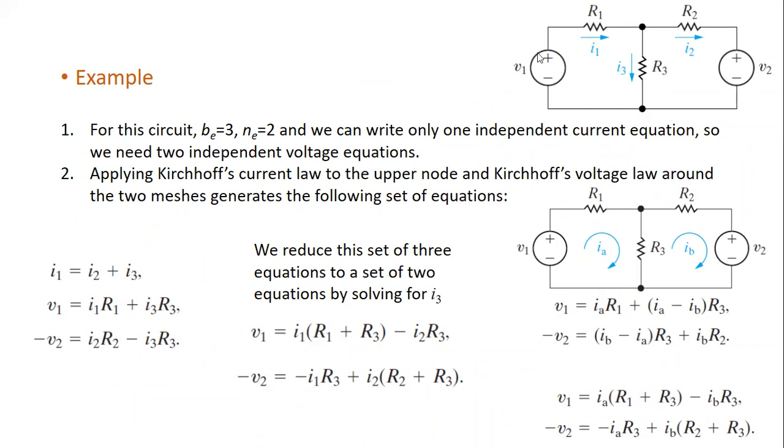And this network is also a circuit because I have at least 1 closed path. And this circuit is active because I have 2 sources. If you have at least 1 source, then the circuit will be active. And I have here 2 essential nodes because this node connects 3 components, and this node connects 3 components.